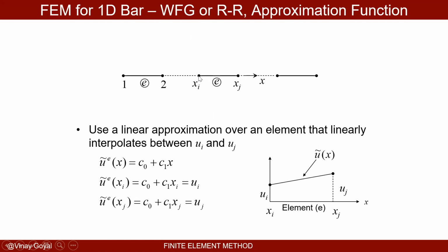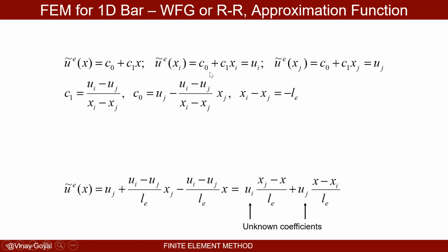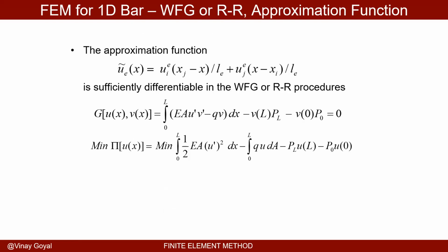This deflection here has to follow the neighboring element deflection. This element here has to follow the neighboring element deflection. So that's forcing my deflection to have to satisfy the essential boundary conditions across the element, so that I can satisfy the fact that across elements the deflections are the same. So that's forcing the issue there.